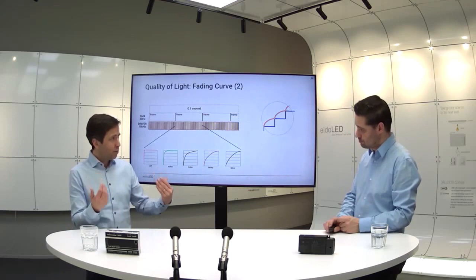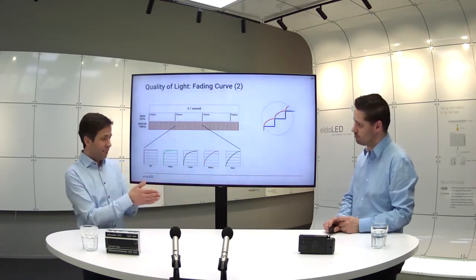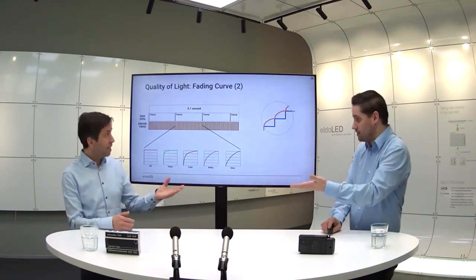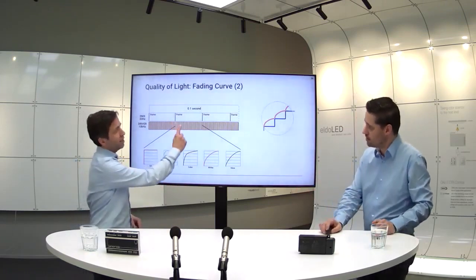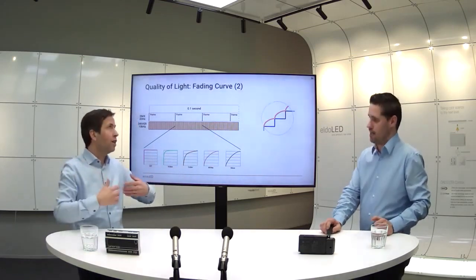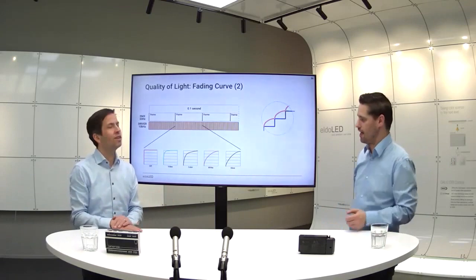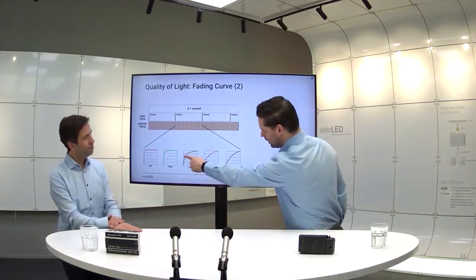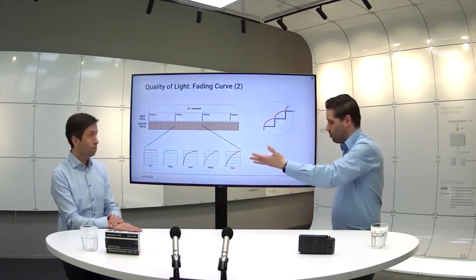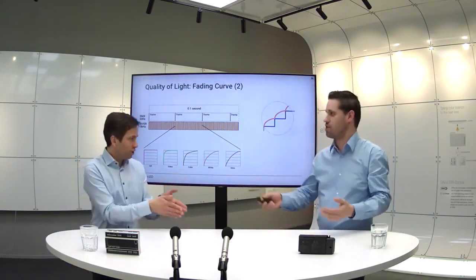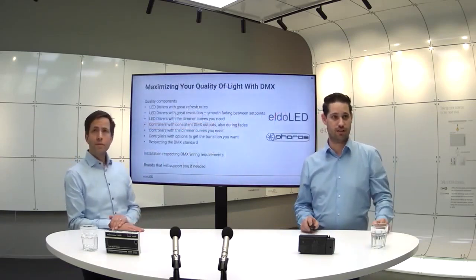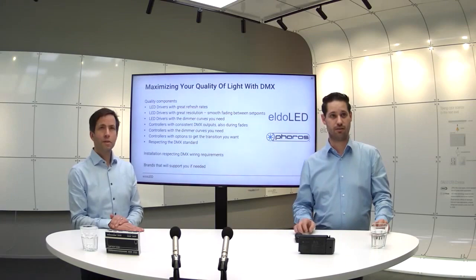And I think going back to the example from the theater, right? In DMX, let's say you have a controller that's set to 8-bit. I can send you 0 or 1. There's nothing in between. And that's a huge step. Exactly. If I understand you correctly, you are making sure that in between it's still going smooth, and the light goes on but people don't actually perceive that it started. Exactly like that. And we also do that via a different curve, more or less similar but at a much smaller frame. That's the transitions in detail from an LED driver perspective.